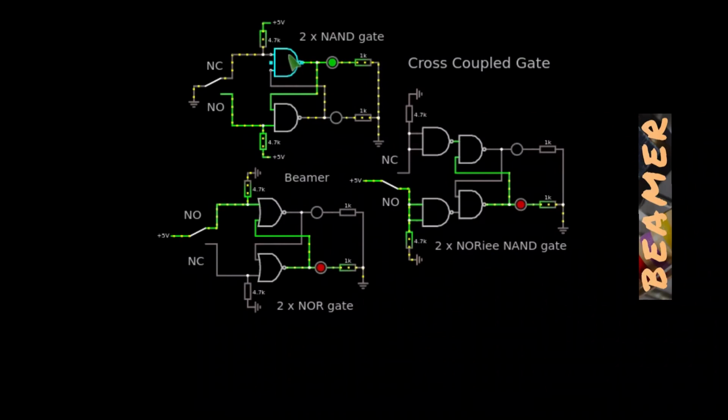The advantage of this, of course, is that you've only got one rise time and one fall time for an actuation of the micro switch, and so therefore it doesn't matter how this bounces on the contacts. The output of this only produces one fall and one rise.